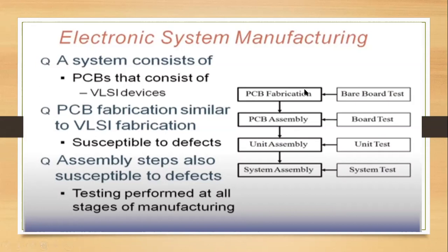So when you are going to test any PCB fabrication process, that is said to be a bare board test. So what will we be doing in this PCB fabrication test? You'll be checking within the PCB whether each and every wire connection from each and every pin is correctly connected or not. That can be verified over there. Bare board test means each and every wire connectivity between each and every lead or pin section is connected clearly or not, and that is going to be verified. Bare board means without placing any component, you are going to test the PCB.